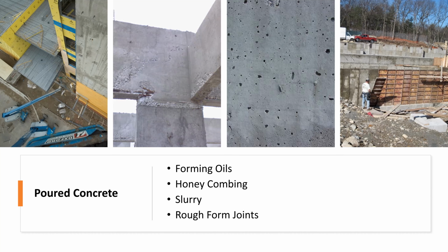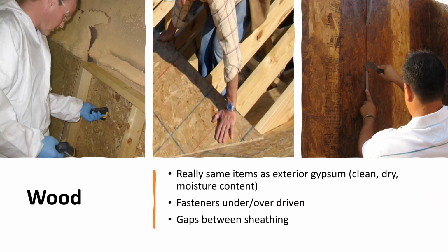All these materials like this nice smooth substrate. As soon as stuff gets a little bit wonky, it's not a big fan of it. But if you use something like a spray foam on this, that's going to be able to deal with those undulations and that uneven surface. So depending on the system you're using, some of that honeycombing may be an issue, and sometimes it may not.